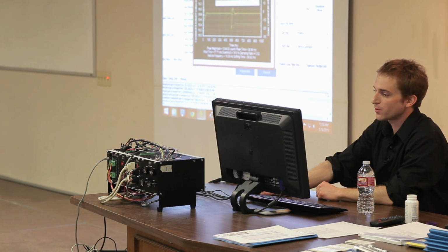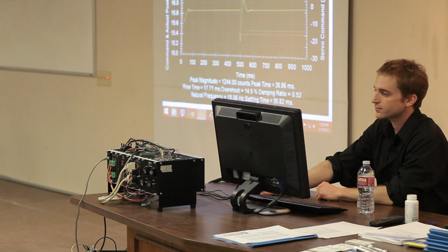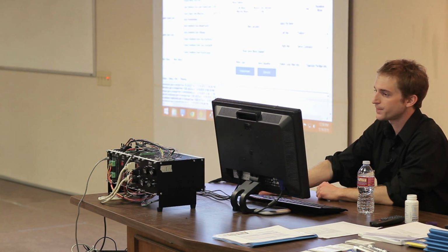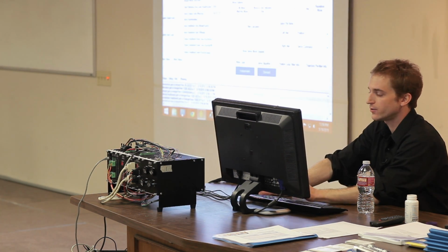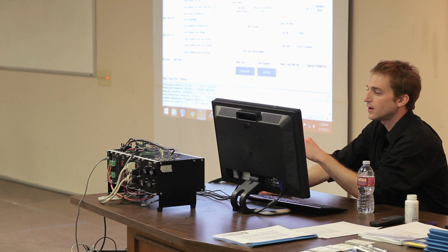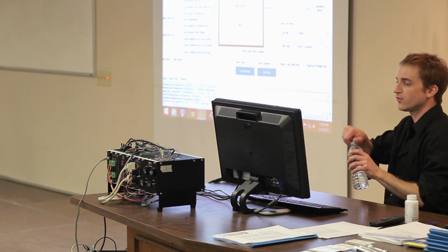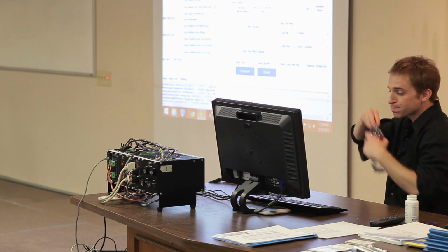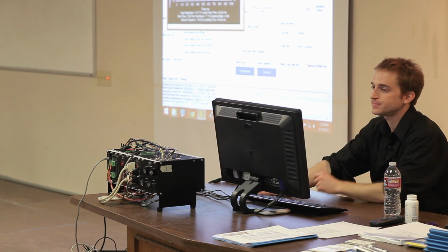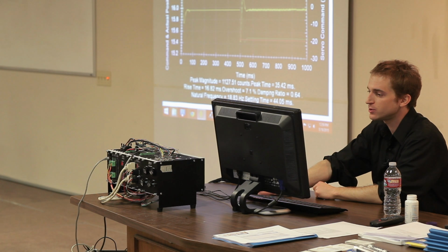Now that gap is getting smaller and smaller compared to before. So just continue iterating the process of increasing Kp and KVFB. The gap continues to shrink.